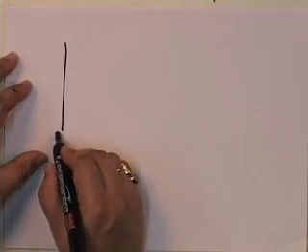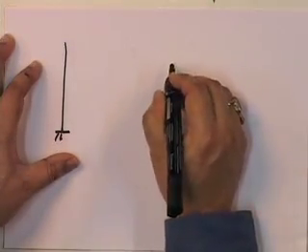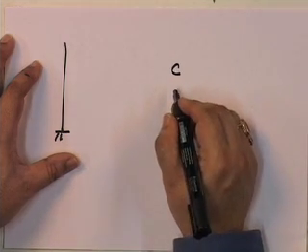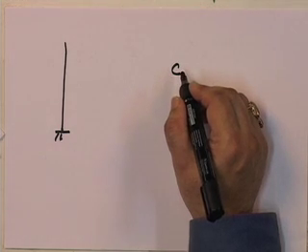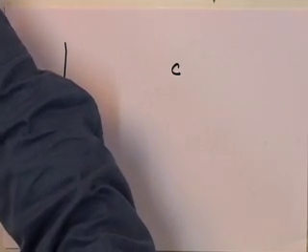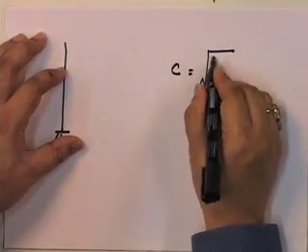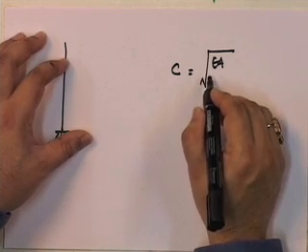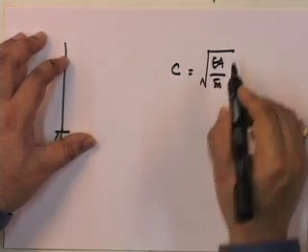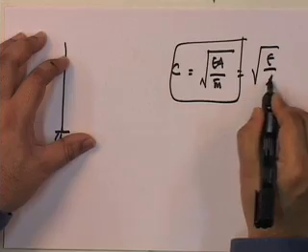If I make a plot of the displacement, and I define a parameter called C, where C is equal to the square root of EA upon m bar, which is actually equal to the square root of E upon rho.